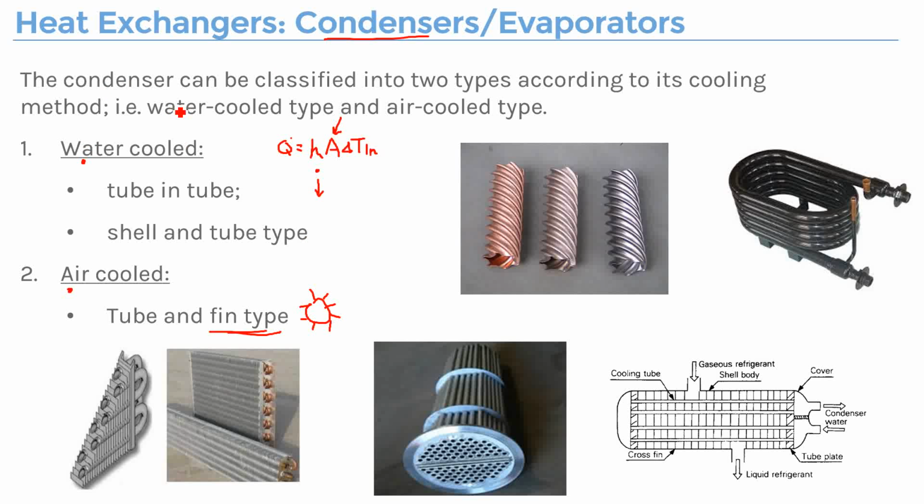So, yes? Can you talk us through which one is tube-in-tube and shell-in-tube? Yeah. So this one is the tubes inside the shell. It didn't draw the shell for you because if it has a shell, maybe you cannot see the tubes. But basically for this one, it's similar to this. You have many tubes inside, and a big shell around them. So you have fluid flowing from one side, and the other liquid flowing through the other side.